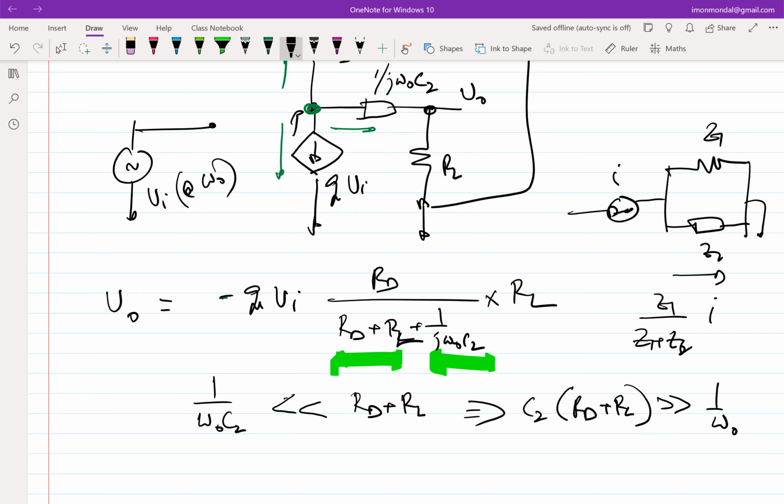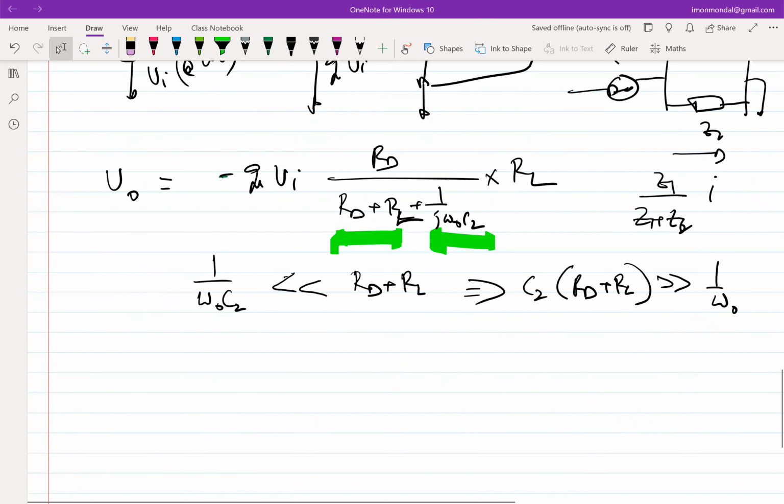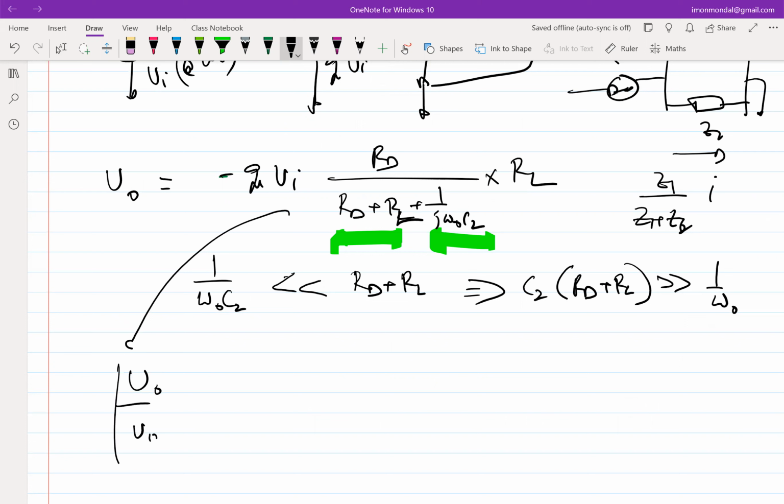But the thing that sometimes trips students up is exactly the question that you asked. Hey, we have learned time constant when you give step inputs, and this omega naught comes about when we were giving sinusoidal inputs, right? So what is the relation? The relation is essentially the fact that if you sketch the Bode plot of the transfer function, what will be V naught over Vi? What will be the transfer function in this particular case?